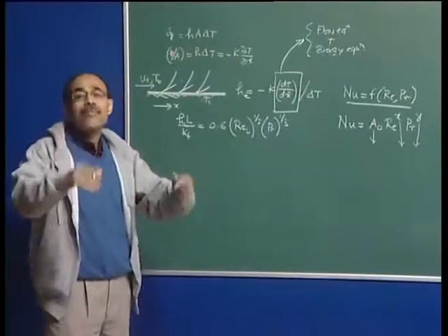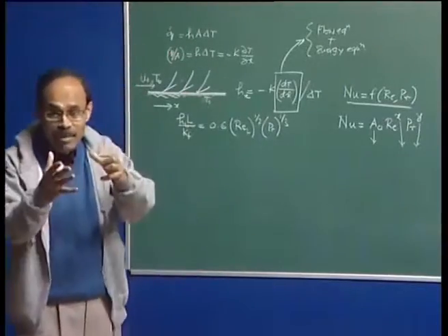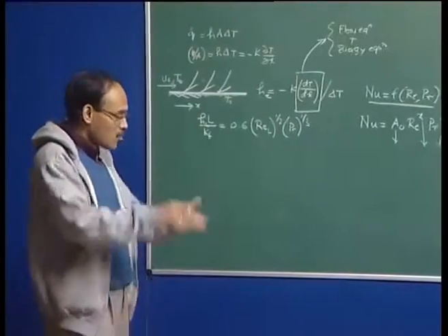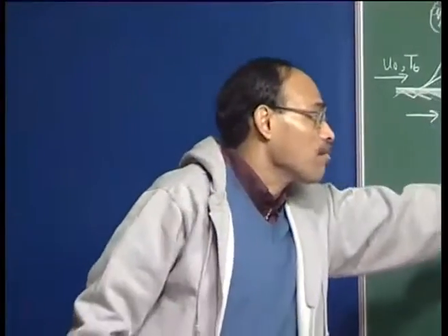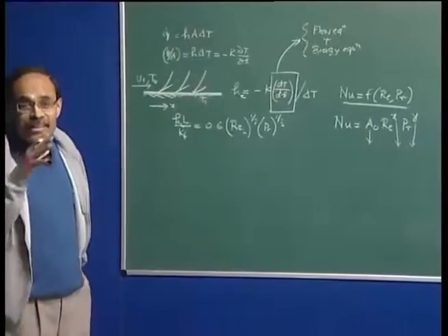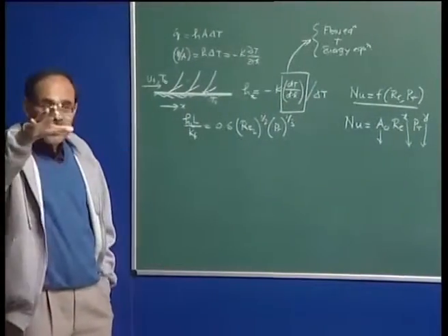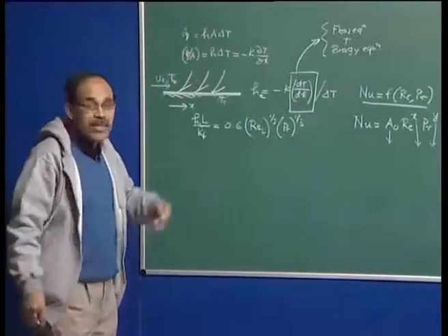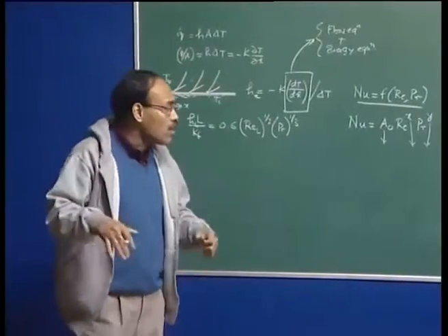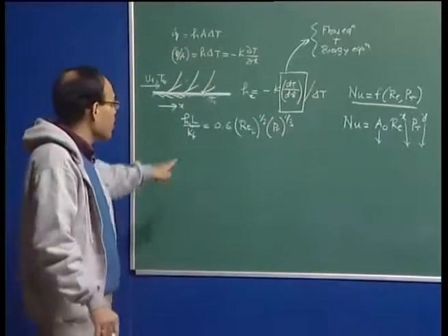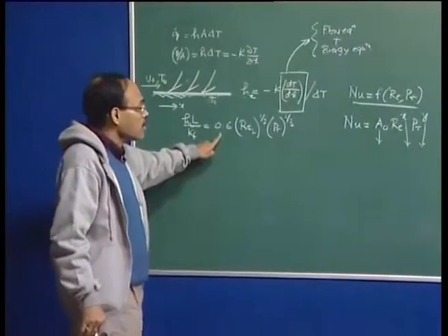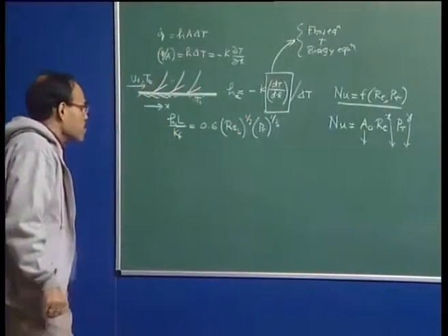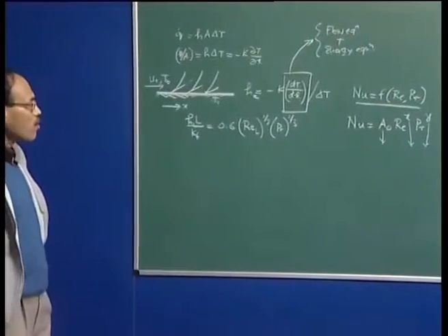So, the characteristics of the boundary layer are going to be different, because Prandtl number is a ratio of momentum diffusivity to thermal diffusivity. So, the characteristics of the boundary layer are a function of Prandtl number, and we will anticipate that the characteristics of the boundary layer in molten steel systems and air water systems, okay, in which the flowing fluid is air or water, are going to be somewhat different. So, there is some element of uncertainty when we apply this kind of a correlation in a straightforward fashion to steel making systems. So, I think enough is said about convection.